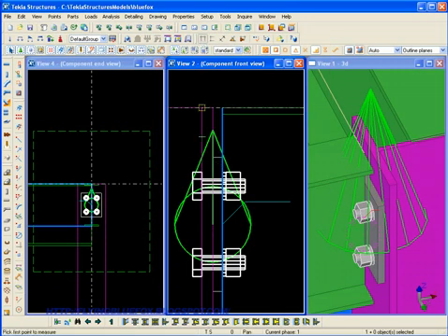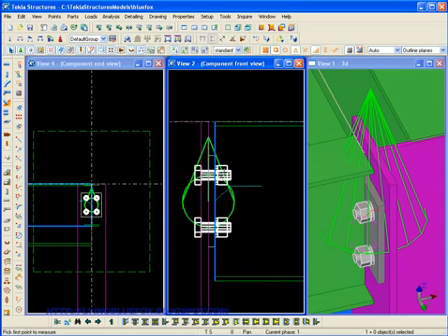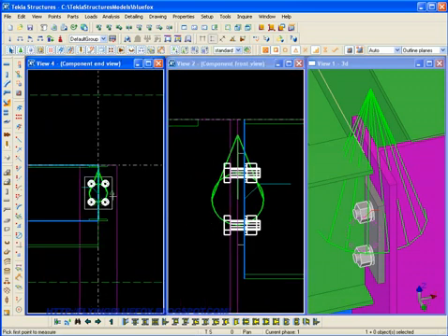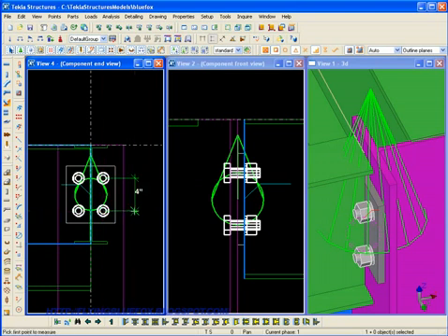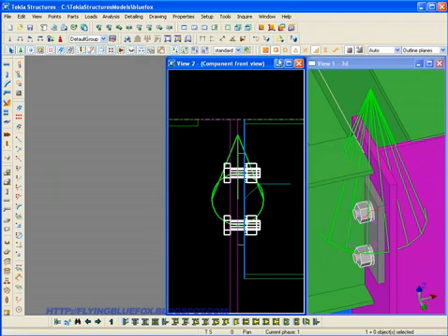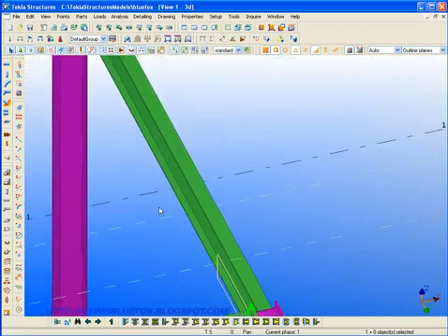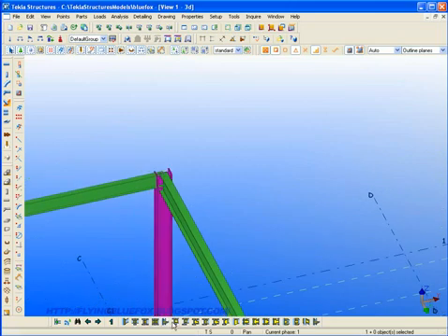Now we can pick, as you can see, it's 1/2 inch, and our spacing should be 4 inch. There you go, 4 inch. If you go to front view, that should be 3 inch. Yep, end plate. Let's close down that, leave your 3D open. Now let's add a shear plate. Go to page 1, shear plate sample number 146.